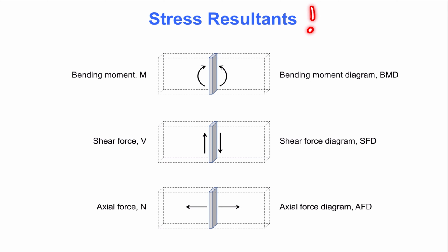These resultants of axial and shear stress are expressions of average stress. More precisely, they represent the integration of stress on infinitesimally small portions of the material over the entire beam cross-section. These stress resultants, including bending moment, shear force, and axial force, appear in capacity formulas in every design standard for various materials. In other words, the structural engineer usually employs resultants of stress over the cross-section to check that the capacity of the structure is sufficient.